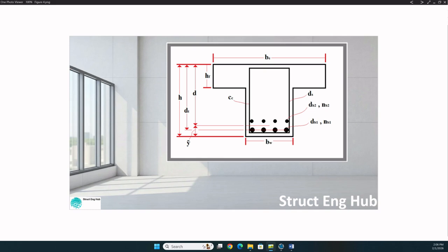But if the beam is an edge beam where slab is present on one side only, the beam will have an inverted L-shaped cross-section. Today we will deal with flanged sections carrying positive bending moments, as we will deal with those carrying negative moments in another session.